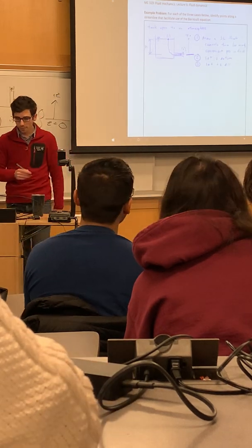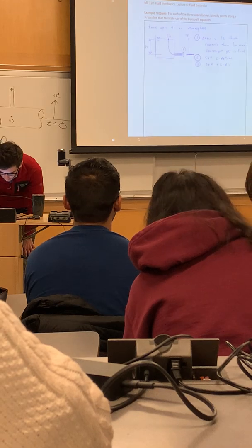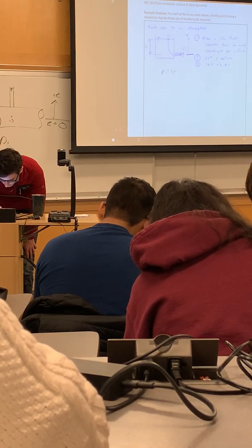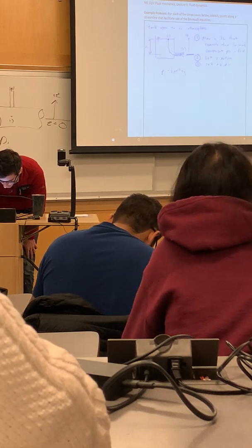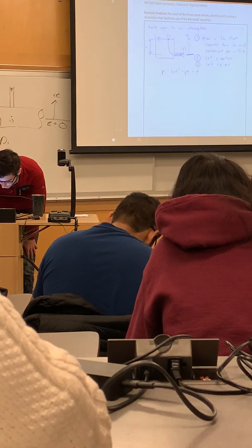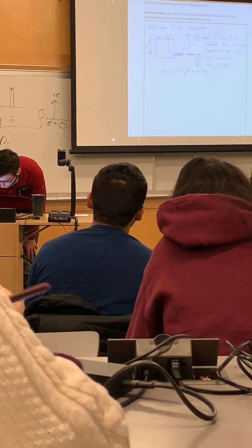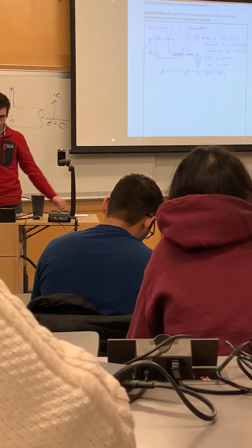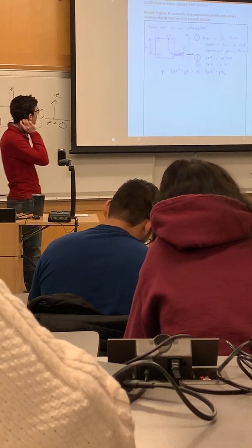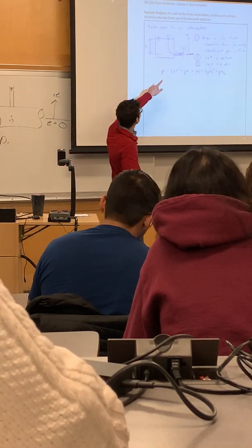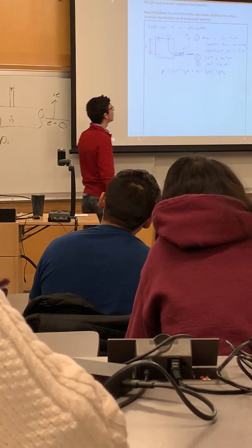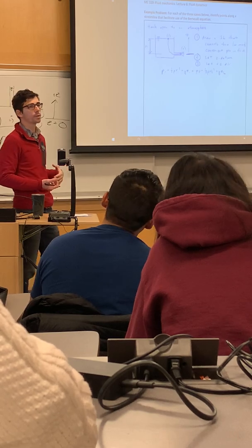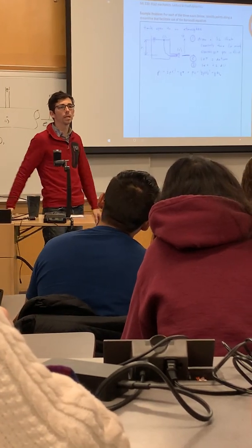Okay. So if we were to apply our Bernoulli equation, right, we have P1 plus 1/2 rho V1 squared plus gamma Z1 equals P2 plus 1/2 rho V2 squared plus gamma Z2. Okay, so that's our, we're invoking Bernoulli equation across the streamline from point 1 to point 2. I think as you work these problems, you'll get better at this, just like you do with manometer questions. You can probably immediately see what cancels out.